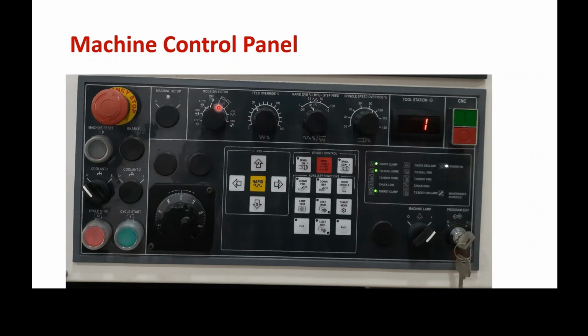If you want to move manually along the X direction, you have to keep it in X. Then in X, you can move in the positive direction and the negative direction. For that, you make use of this knob. If you rotate towards the left and keep it in the X direction, you will achieve movement along minus X. That is, the tool will move downwards. Suppose you keep it in X and move towards the right, then the tool will move upwards. Similarly, if you keep it in Z and move towards the left, the tool will move towards the work part. If it is positive, it will move away from the work part. That is the meaning of MPG mode.